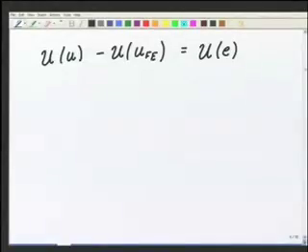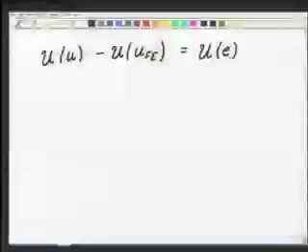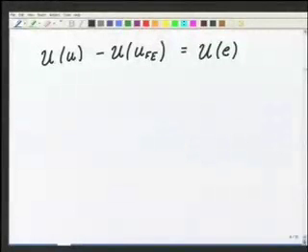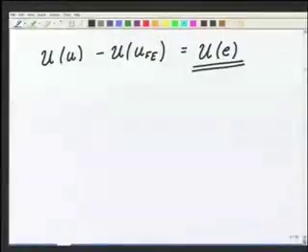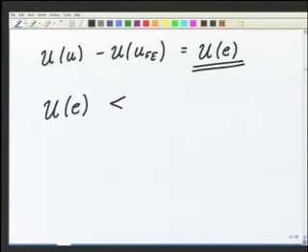That is, as UFE goes closer to U, U minus UFE becomes smaller and smaller. Because of that, the strain due to the error, which is U minus UFE, becomes smaller and smaller. When the strain becomes smaller, the stress becomes smaller, so this also becomes smaller. So as my finite element solution converges to the exact solution, the strain energy due to the error should fall down. Question is, at what rate? So UE comes down at what rate?